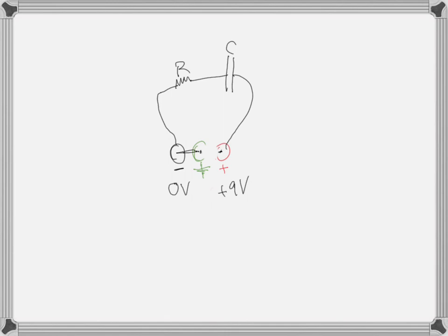So you can ground either side, and we will actually find where we want to sometimes ground the plus in order to make our voltages negative, or ground the negative in order to make all our voltages positive. In general, we're going to do it the way shown right here. So if you ground the negative, then all the voltages are higher than 0 throughout the circuit. And remember that this is the same as drawing this voltage to resistor to capacitor to ground, where this is 9 volts and this is 0 volts going down.